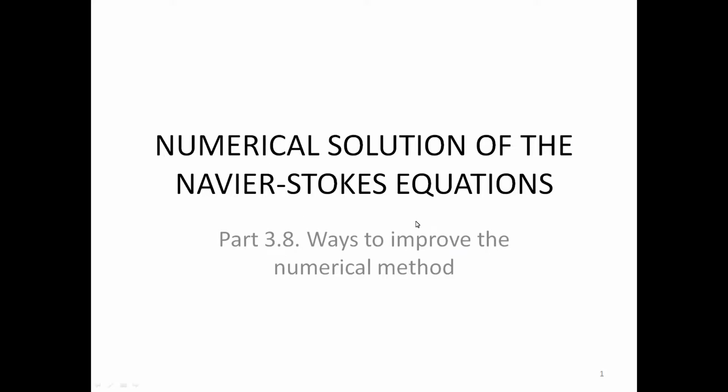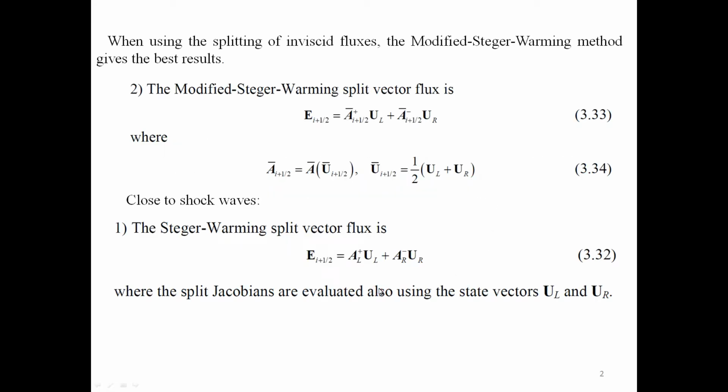Let us study the last part of the numerical solution of the Navier-Stokes equations chapter. This part is called Ways to Improve the Numerical Method. When using the splitting of inviscid fluxes, the best results are achieved when the modified Steger-Warming method is used.